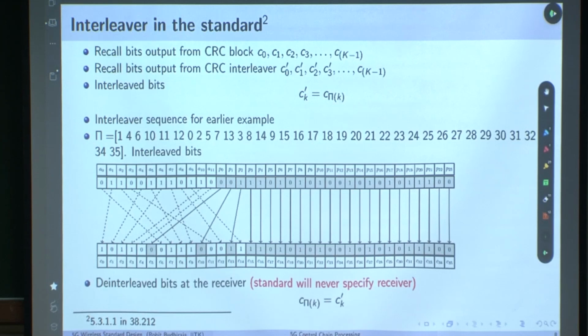The user has to do this multiple times, depending on subcarrier spacing. It has to do it 36 times. If you keep doing it, then it's a waste of energy, not even required. This is a philosophy. All this control chain, we have always been talking about the reduction in complexity, and we know why. This is one key aspect. The other key aspect which we learned in these classes is polar decoding, and that works well for lower code block length, which in the case of DCI is much lesser than the PDCCH.